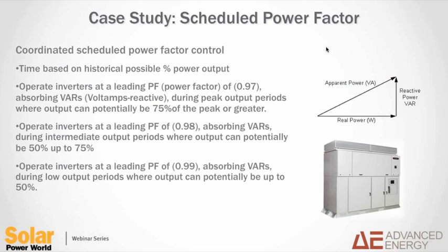So to get into one example, here we have a case study of scheduled power factor. The situation here is that the photovoltaic plant actually represented a significant capacity on the particular feeder that it was installed, in some cases 50 to 75%. So at the time, the utility didn't have the ability to directly communicate with the inverter, so they conducted studies and they wanted to be able to ask the inverter to do certain things at different times of the day, as well as different times of the year, because load profiles change based upon seasons and time of the year.